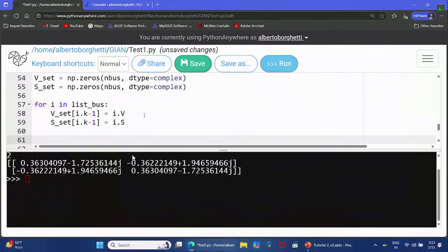So what are the inputs, what are the outputs? In this problem, you see that you cannot classify the buses as the normal PQ, PV, slack, because in this bus, you fix the active power, the reactive power, and also the voltage.